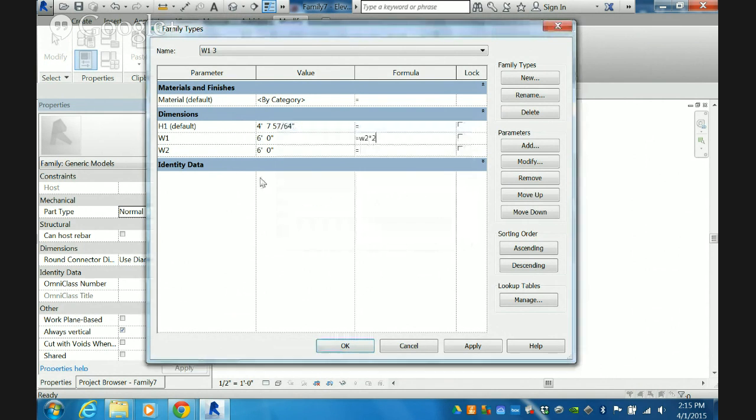W2 is not a valid parameter. FYI, whenever we do these formulas and we're referencing back to these parameters, it's case sensitive. So I did lowercase w, I want it to be uppercase W. And it goes. And then of course I can change this value here. It will automatically start updating that. And of course it goes both ways, so I can adjust one or the other. Make this guy 2 and do whatever.